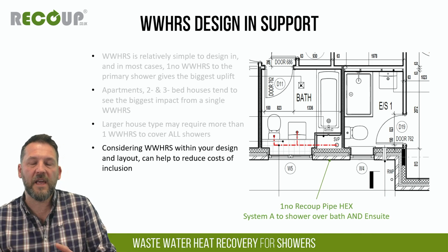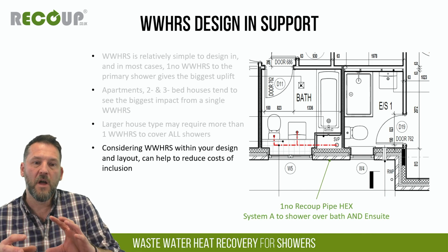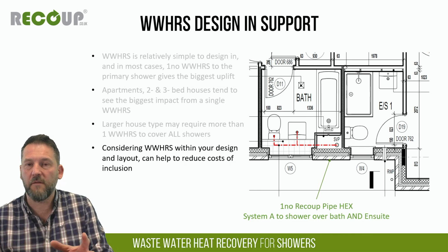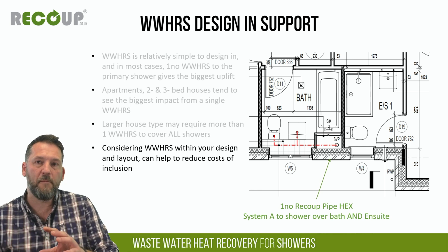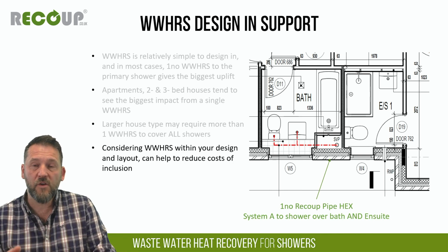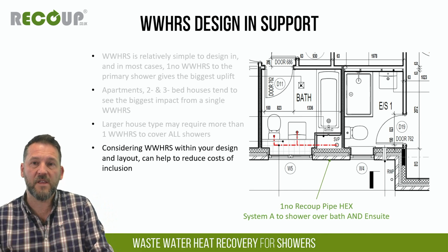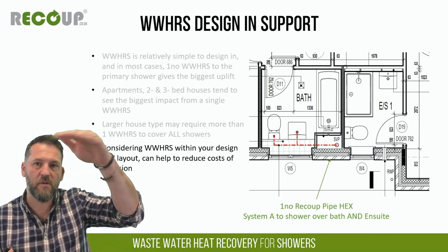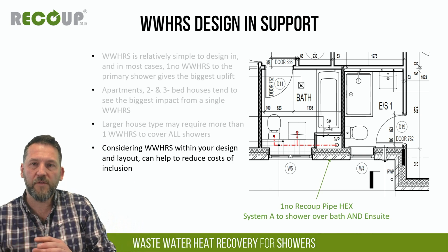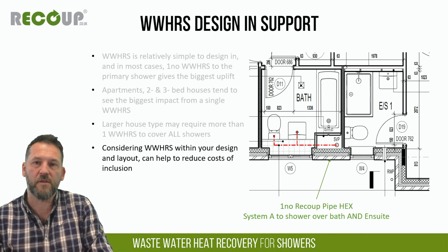But certainly if you can look at designing bathrooms reasonably close together, within a few meters of one another, back-to-back showers, en suites and bathrooms for example, they can normally benefit from both waste going into a single pipe, or as I said earlier, with stacked showers on townhouses. So often two showers might be able to install to a single vertical pipe, and that then maximises the cost efficiency, keeps the cost down, keeps the SAP points high.